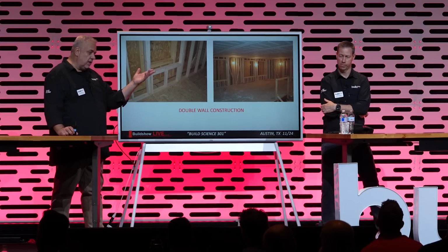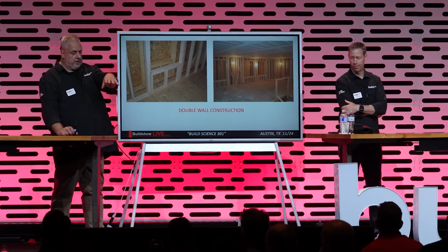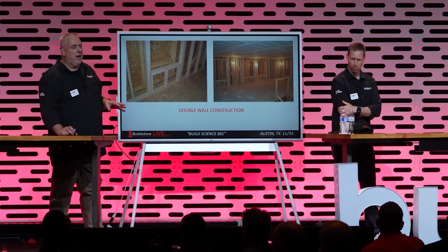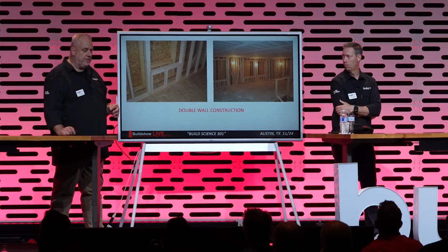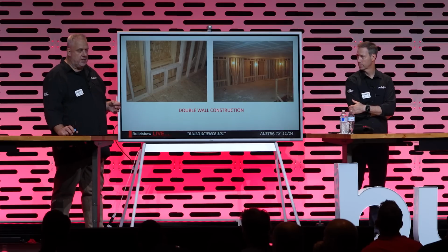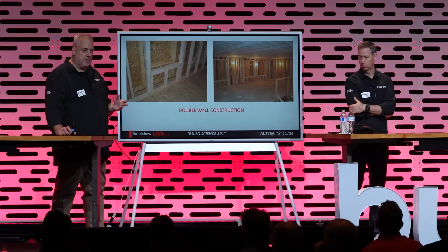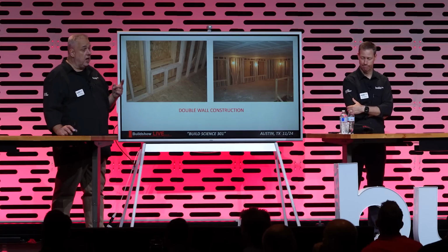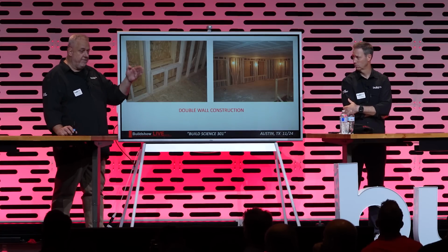Air barrier, yeah. So just so you know, I talked earlier about this house, zip green box. We did the drywall on the lid, concrete slab. We hit 0.16 ACH 50 on the house. Wow. So any of you that are concerned about zip not making the grade or really isn't an airtight system, I don't know what to tell you, but 0.16 speaks a lot. That's tight. It also speaks to, we didn't cover any of the field nails. And I know a lot of people are worried about, what if water gets in there? Well, you need a hole, you need water, you also need a pressure difference. So if I'm hitting 0.16, understand I don't have the pressure difference. If I don't have all 3, I don't have a leak.